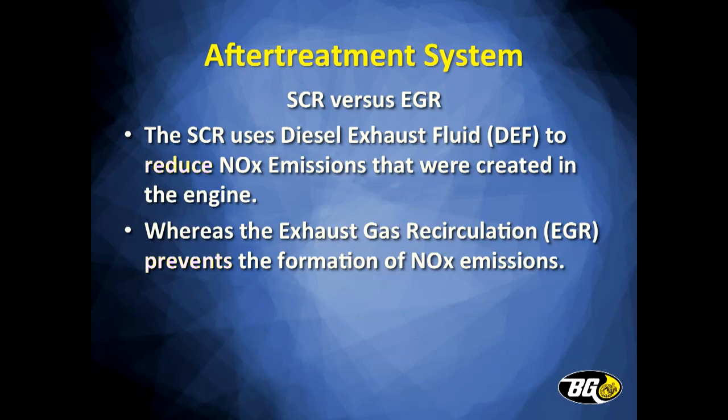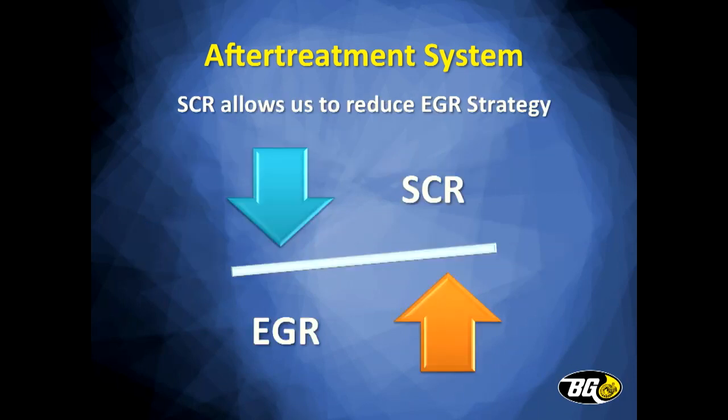And if you remember, in the EGR, it cools the combustion chamber. So if we could reduce the EGR by having more SCR, you can actually help to reduce some of the soot that's being created inside that engine before it heads to the tailpipe. That's the purpose of the SCRs.